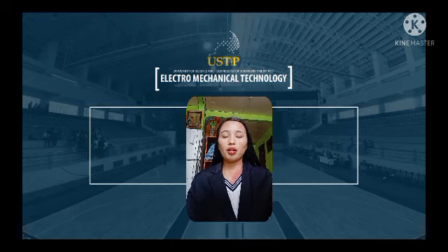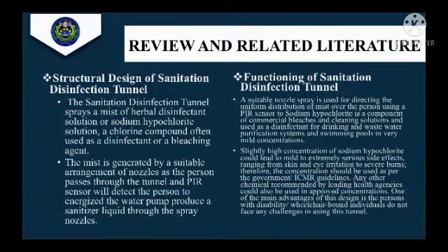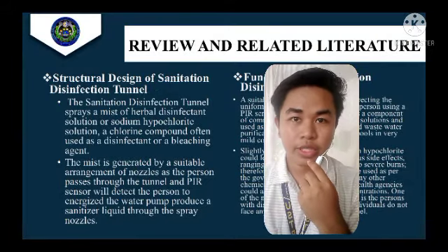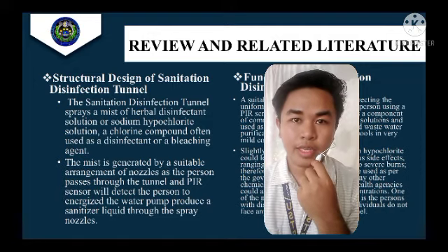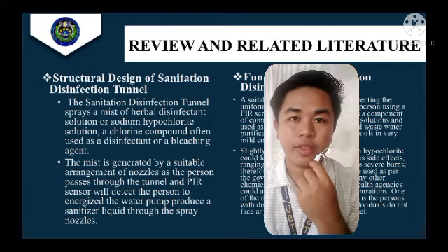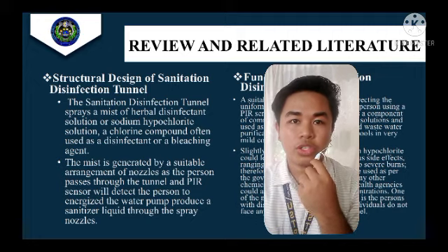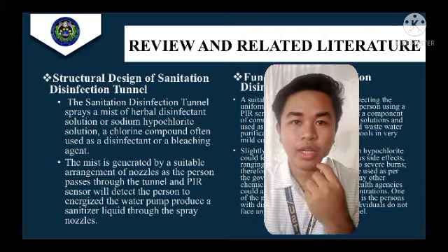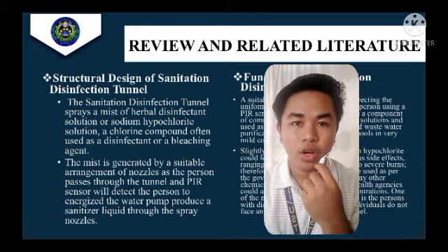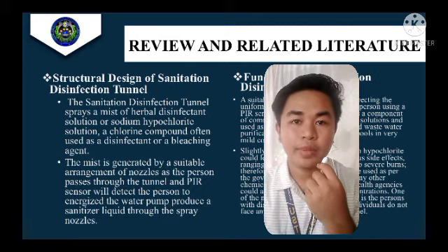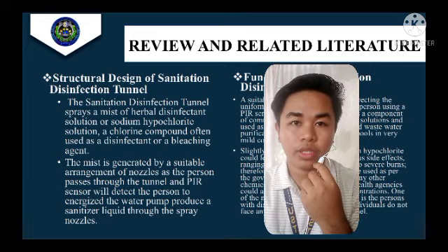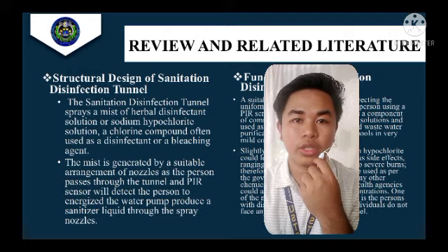I'd like to move on to our next topic. That leads to Will McKinley Badilla. Structural design of the sanitation disinfection tunnel. The tunnel is placed in a mist of herbal disinfectant solution or sodium hypochlorite solution, a chlorine compound often used as a disinfectant or a bleaching agent. The mist is generated by a suitable arrangement of nozzles as the person passes through the tunnel, and a PIR sensor will detect the person to energize the water pump, which produces sanitizer liquid through the spray nozzles.